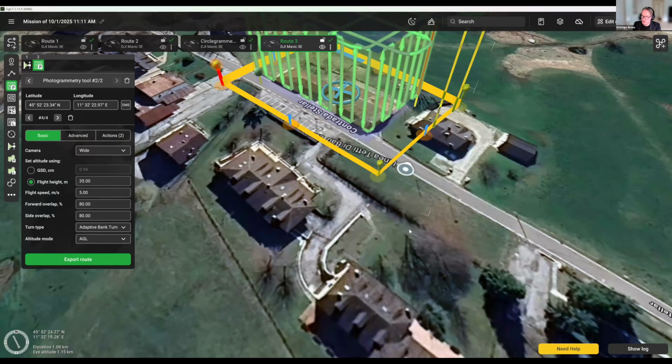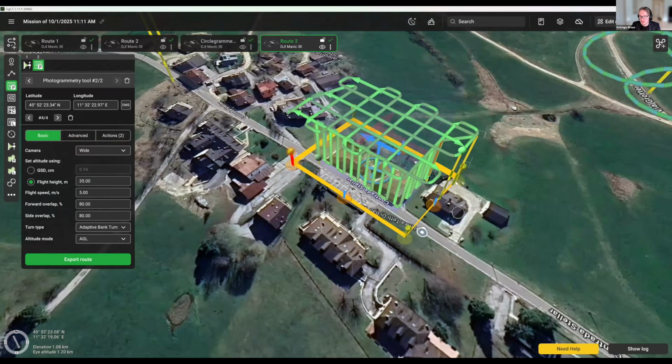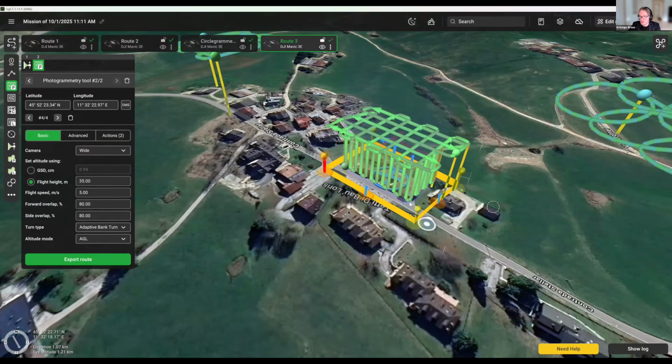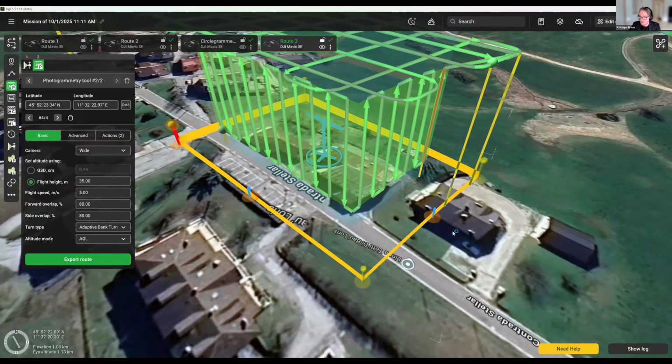So what you can do in those situations is cover a certain part of the bottom side of the building manually, just by manually flying the drone and taking pictures. And then from the level where the trees stop, that's when you can use automation to get more consistent results. But yeah, this is basically how you can plan vertical missions for buildings.